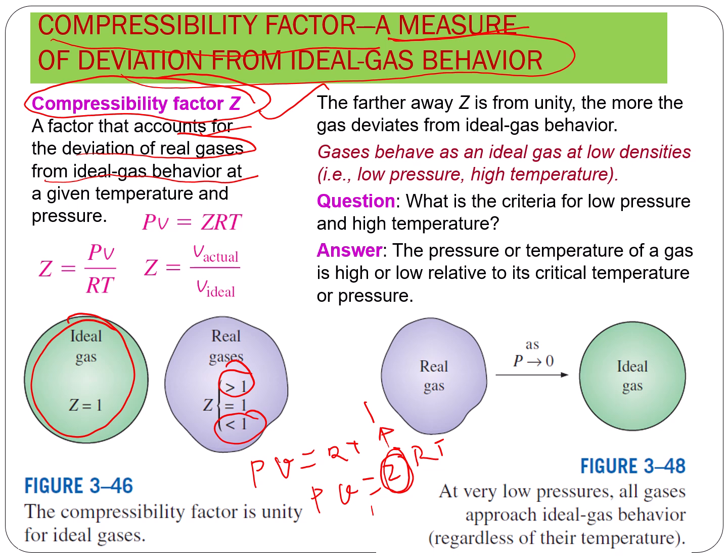You need to understand that the ideal gas equation cannot be used for any gases. It holds true for ideal gas. The property is close to ideal gas when the compressibility factor is close to 1. If you write PV = RT, this becomes V ideal, so Z = V actual over V ideal.